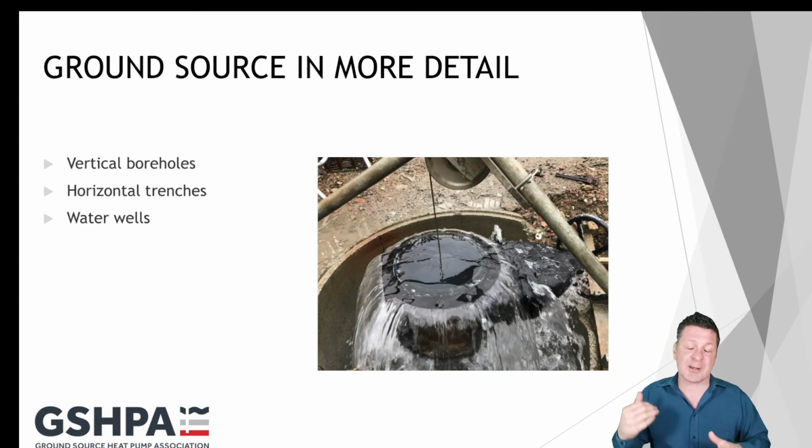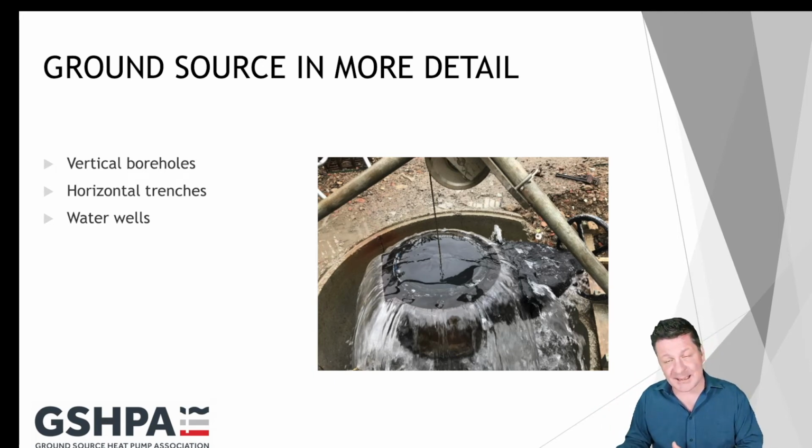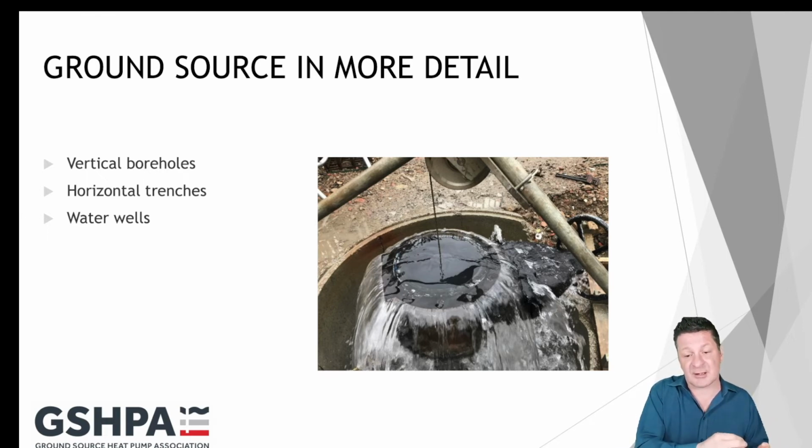So any time that the consumption is over 20 metres cubed a day, a statutory licence would be required in England and Wales. The rules are slightly different in Scotland, where SEPA can actually allow licences provided all the water taken from the ground is put back in. So quite a complex field. It is a different installation process from closed loop, much bigger in construction terms.